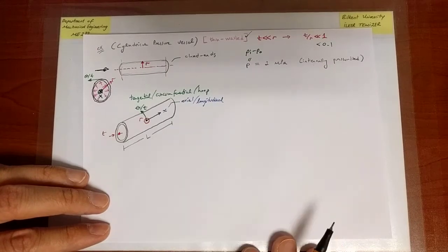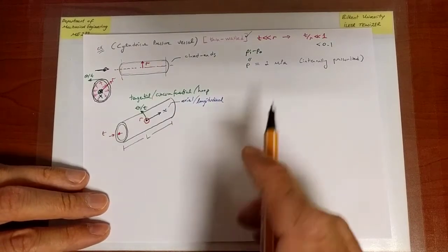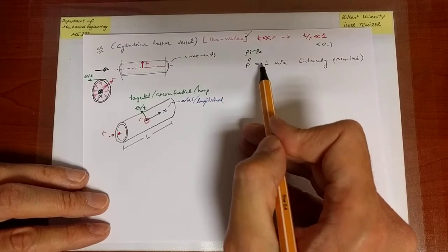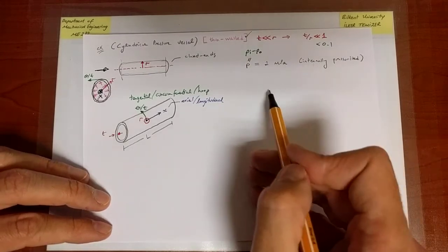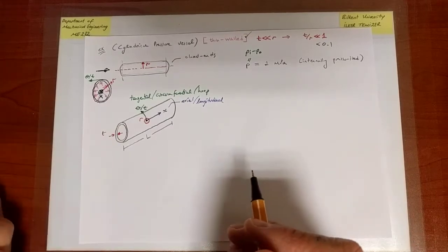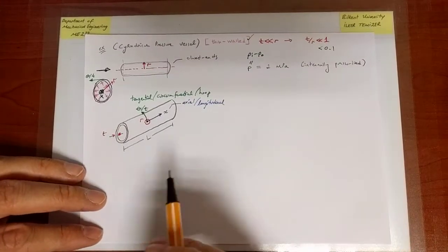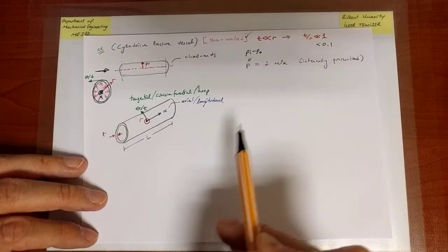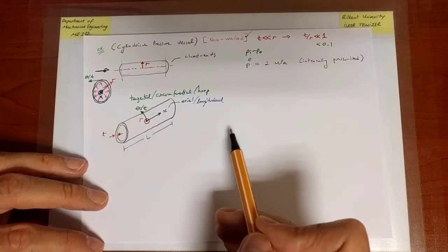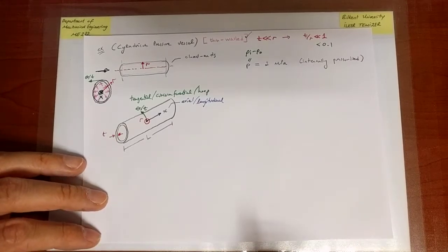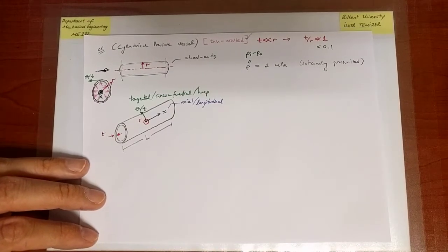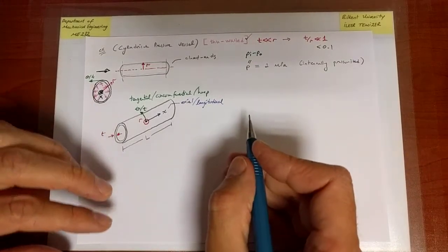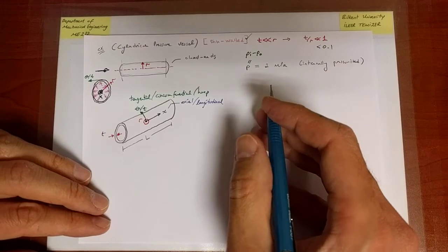Now, having said that, the subsequent analysis is just going to assume that it's internal. If it turns out that it's a negative value, so 2 MPa externally pressurized, you're just going to put a negative value for P in there that reflects that difference, and the whole analysis remains the same. Whether it's positive or negative will influence whether the stresses are tensile or compressive, but that will come through the sign. Okay, so now that's the internal pressure. 2 MPa, no big deal.